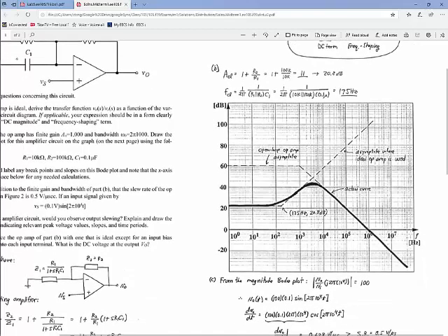The next stage was plotting the Bode plot for that circuit when the op-amp is not ideal. For this, what you really needed to do was first plot the Bode plot for an ideal op-amp, which would have been this going across and this going all the way up, and then plot the op-amp Bode plot and have them intersect. Where they intersect, the actual transfer function just follows the op-amp's transfer function. I think a good number of people got that as well.